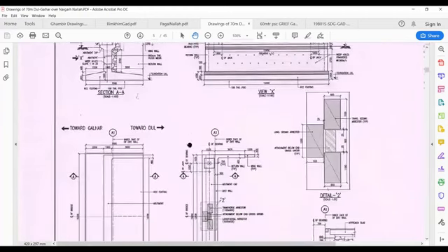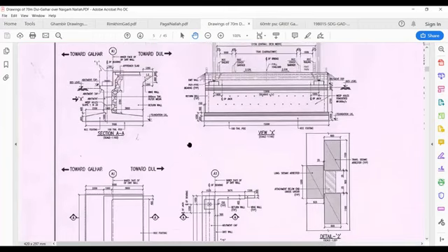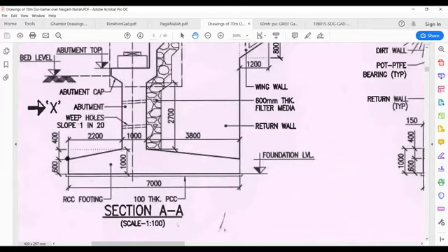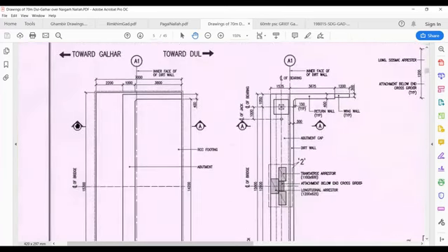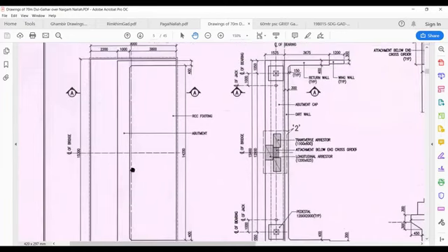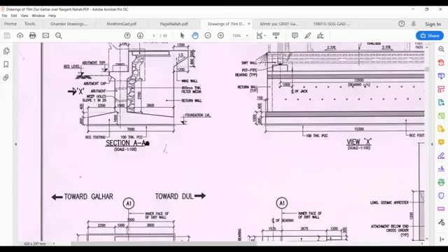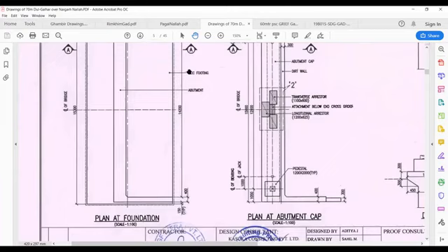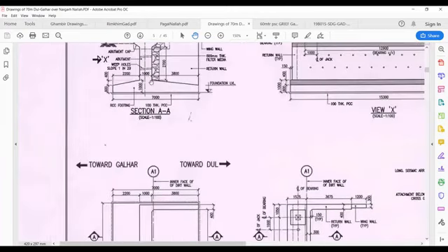अभी estimation के लिए first thing is, the first thing for any contractor is to be able to estimate the quantity of concrete in a bed. Concrete का quantity estimation is simple coordinate geometry mathematics, because your shape is very clear. ये इसको you can break down into triangles, rectangles, and you can calculate the area, and you know the width of the abutment 15,300. Multiplied by width, you get the weight of foundation. इस wall की बारी आएगी, and you know the wall का width is 14,200 plus 400 plus 400. ये wall की width 1000 by 2700 in this case.